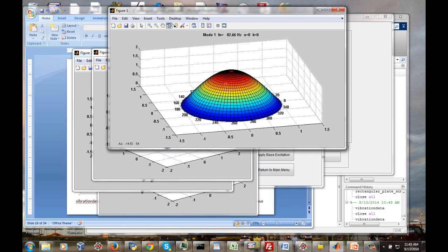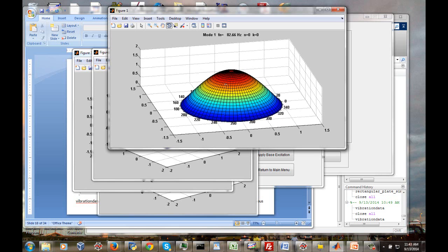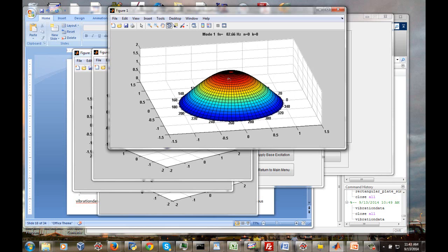And that is there are two stress components in terms of the in-plane stress. There's a radial stress, so imagine the stress going radially outward from the center. Now there's also what's called a hoop stress or circumferential stress or tangential stress. There's also a stress that goes around. So there's the radial stress and the stress that goes around and around and around. Well, I'll call it the hoop stress has an interesting characteristic.